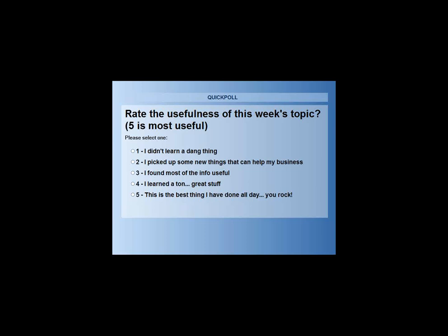Joe asks if Carrier rooftops use the Honeywell W7220, which is that Jade economizer. The non-DDC units that have staged air volume have that Jade economizer standard. Other units still have the old Honeywell economizer, but you can take an option for the Jade if you want it. Once they run out of inventory of their old Honeywell parts, then they'll have to make everything be Jade. The ones that have DDC do not use it. They typically just have a Belimo motor on there, and the DDC circuit board drives the motor directly without having an economizer controller that's separate.